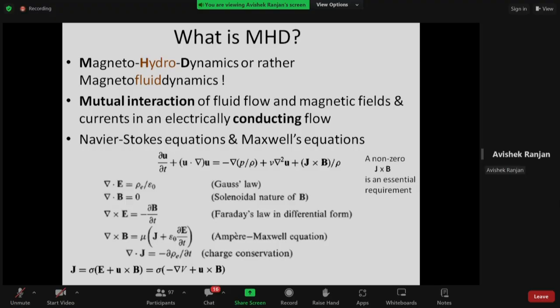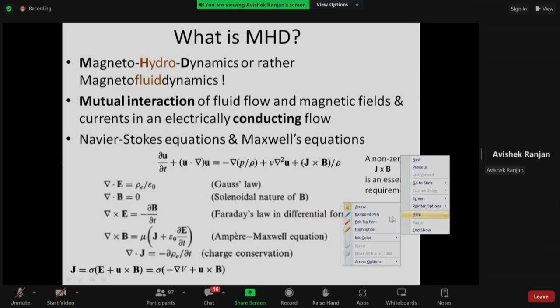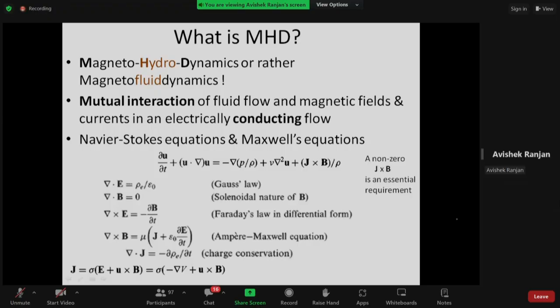So the question was about the Navier-Stokes equation, which you see at the top, and about Ohm's law. I think it's about the electromagnetic equations in general. If you see the equation, the term that I drew a circle on is sort of a new term, because apart from that, this equation is what we already know as the vector form of the momentum equation.